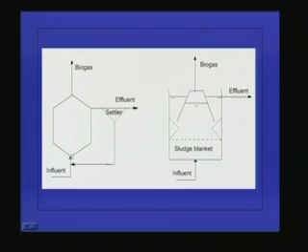So we can see here, the biomass concentration in the system will be very high, so we can reduce the hydraulic retention time considerably. This is known as the anaerobic contact process. Here the anaerobic digester and the settler or sedimentation tank are separate units.